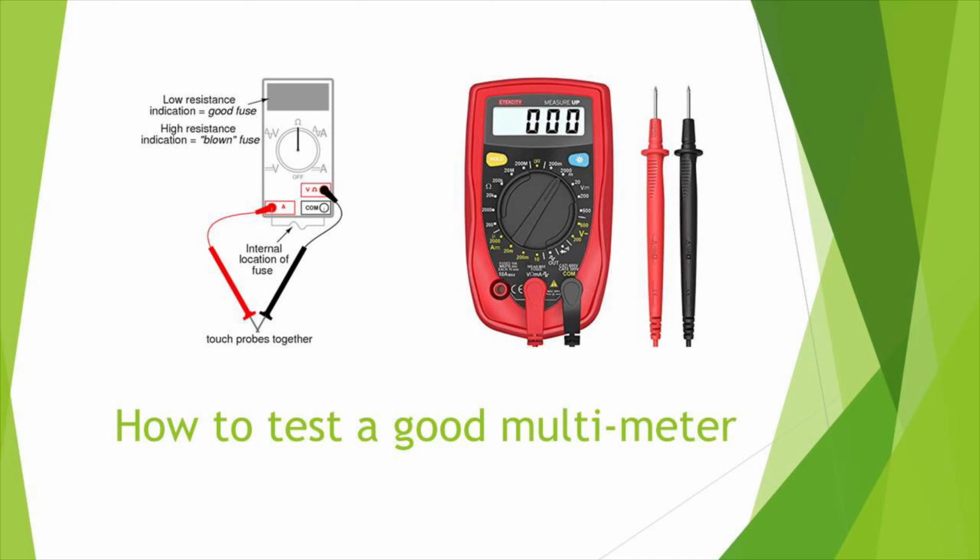This photo shows how to test whether a multimeter is good. You can simply touch the probes together and read the signal in ohms. If you have a low resistance indication, that's a good fuse. And if you have a high resistance indication, it's a blown fuse. So make sure to check before you use a multimeter.